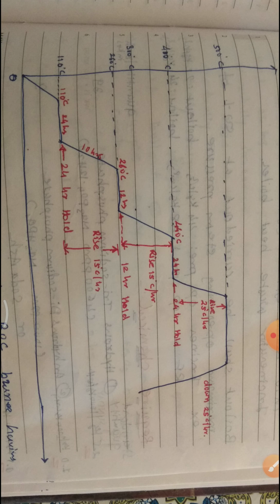During this time, take a sample of IBD and check that phosphate is below 10 ppm. If phosphate comes below 10 ppm, then rinsing is completed, meaning all chemicals are out. So alkali boil out and rinsing are completed.